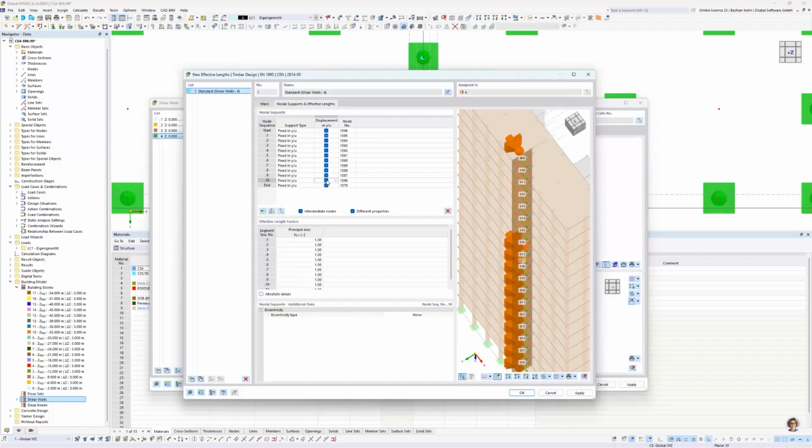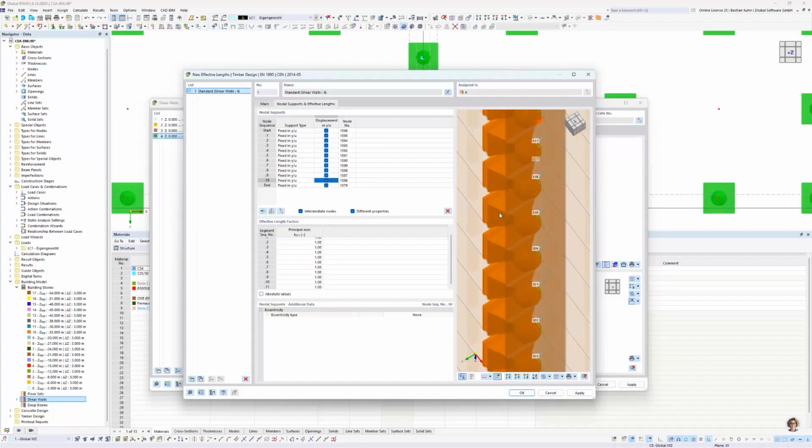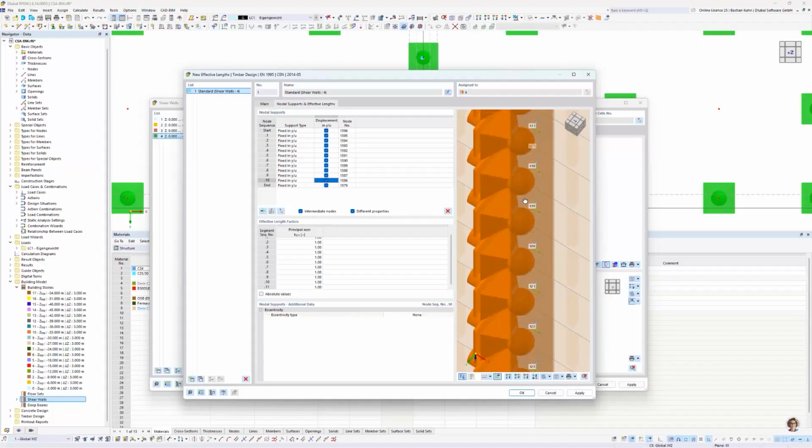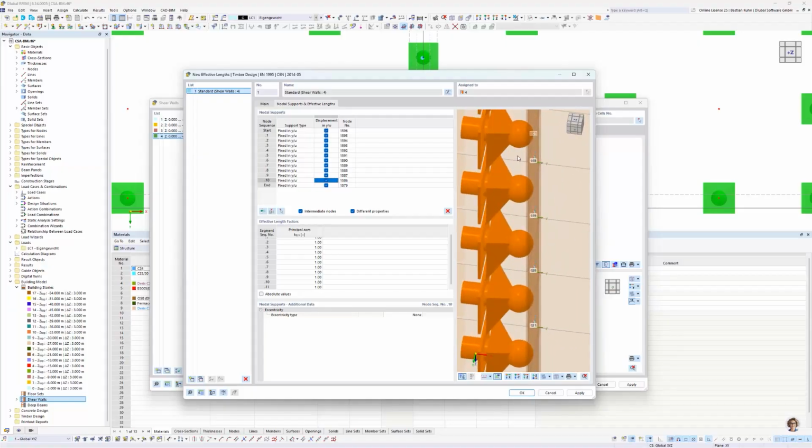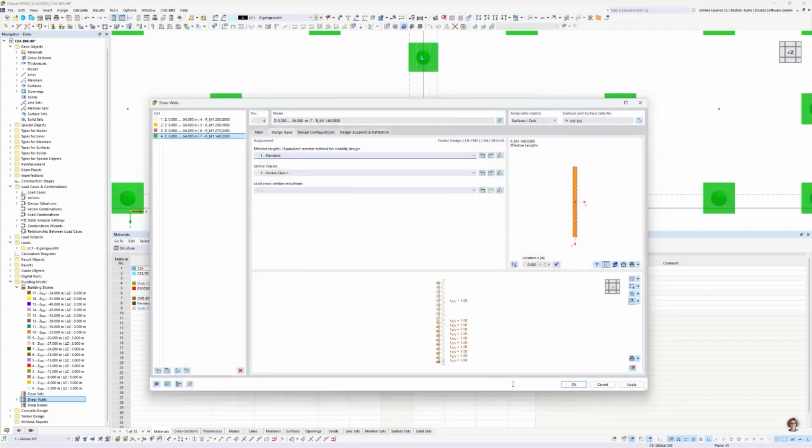Use the minimalizing of the length. So this is possible, so let me just show that here. And now it's supported, and I'm calculating with the effective buckling factor beta equals 1, and do a simplified verification of this.